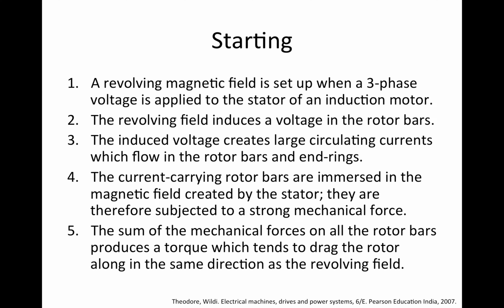Fourth, because the current-carrying rotor bars are immersed inside the magnetic field created by the stator, each rotor bar is going to experience a strong Lorentz force. And fifth, the sum of all the Lorentz forces experienced by all the rotor bars combines into a strong torque, and this torque is going to drag the rotor along in the same direction as the rotating magnetic field.